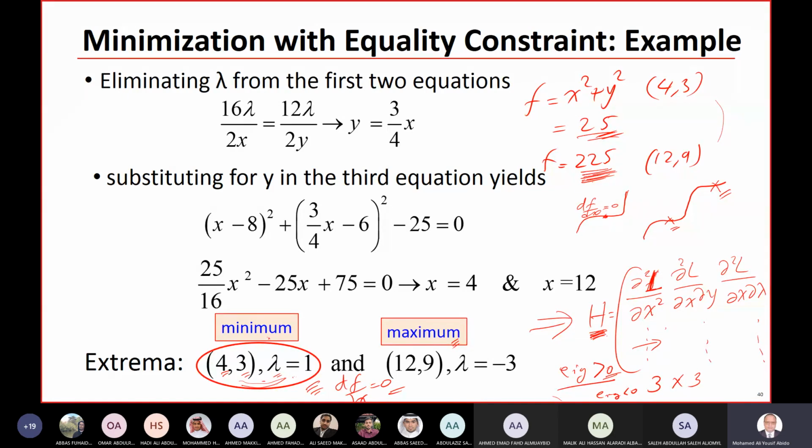let us say, we had a chance to study this Saudi Electricity Company in the Eastern region and we were able to reduce, note, reduce the generators connected to the 380 kV level. The generator is connected through a transformer to a 380 kV bus. The number of generators here in the Eastern region directly connected to the 380 kV network is I think around 31 generators.